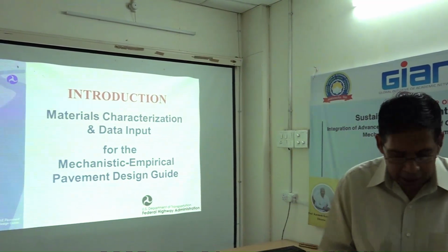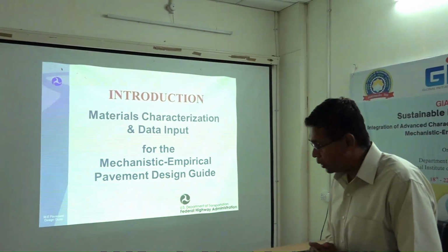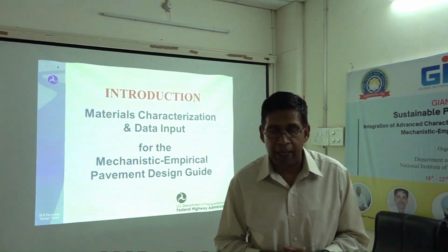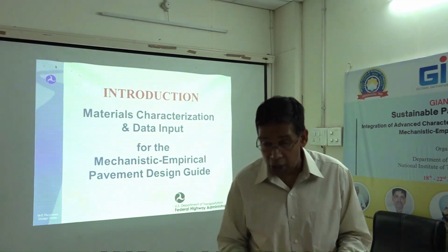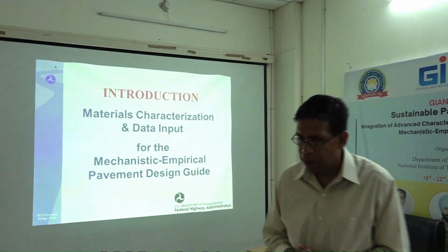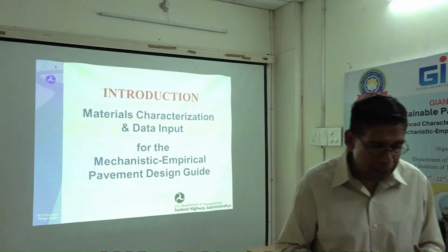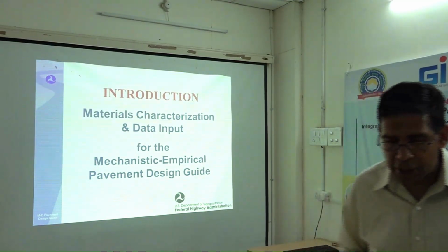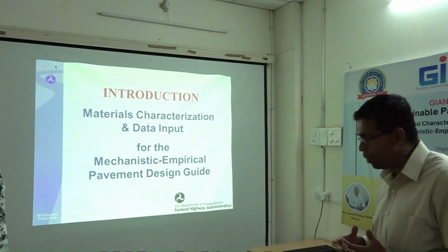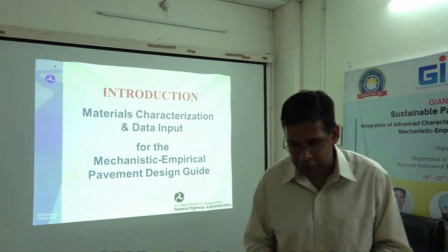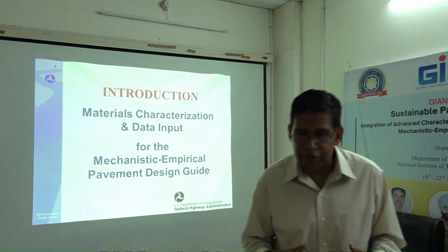So in 1997, Witczak from Arizona State University got a large grant to develop this mechanistic empirical pavement design guide. Now it's no longer called that. It's called AASHTOWare Pavement ME. And he came up with a very comprehensive system to design pavements. And it's not a design tool, it's an analysis tool, and I'll explain that in detail.